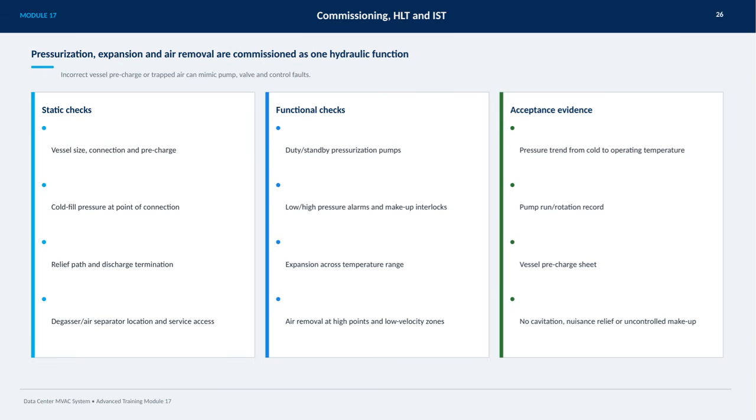We start with static checks, verifying vessel size, connection, and precharge, as well as cold fill pressure at the connection point. We also check the relief path and discharge termination for proper setup, along with ensuring the degasser or air separator is correctly located and accessible for service.